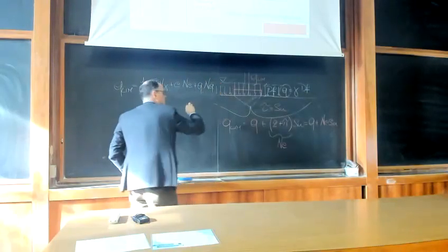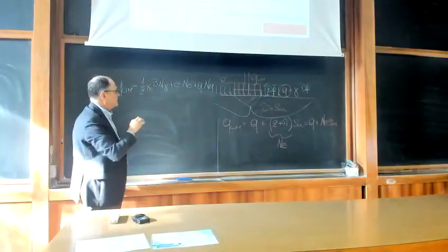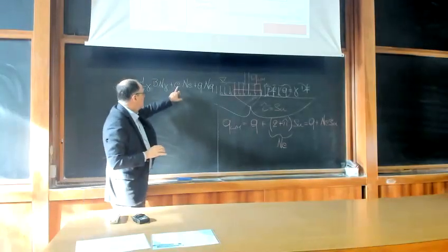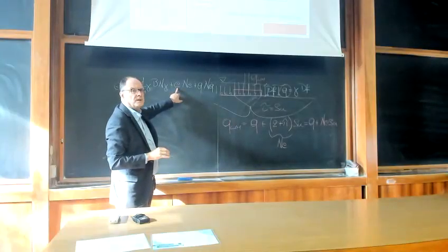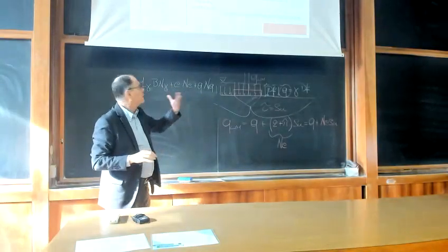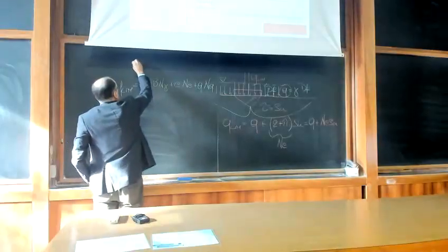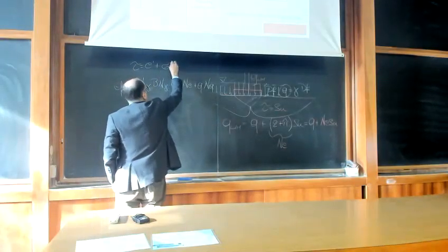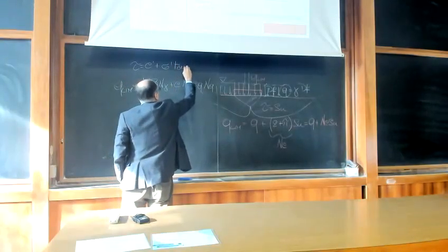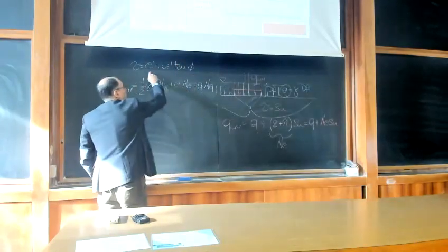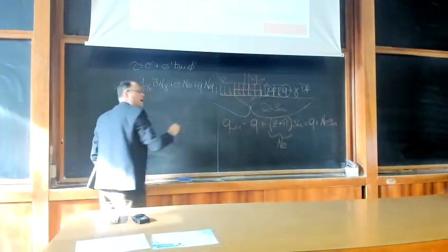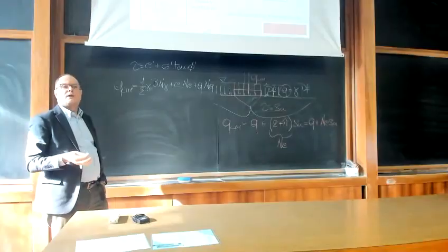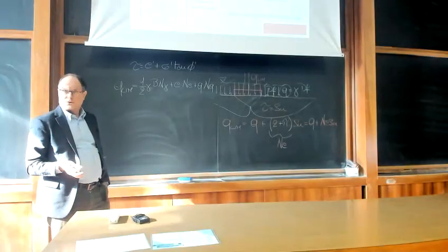Now, we have to understand what these terms are. The cohesion comes from the Mohr-Coulomb criterion. I have cancelled it, so let me write it again: C prime and phi prime are our soil shear strength parameters in effective stress terms.